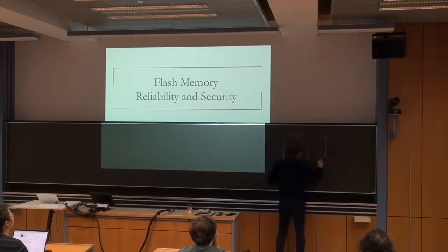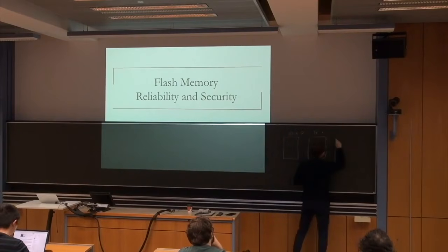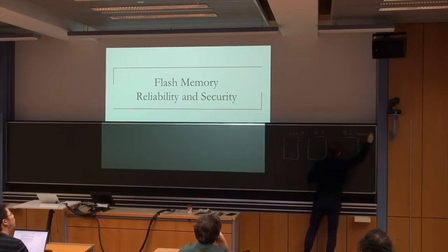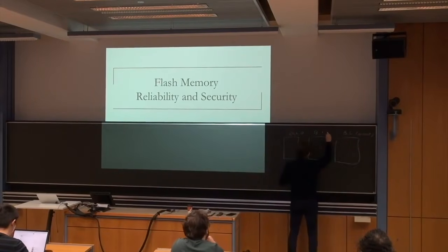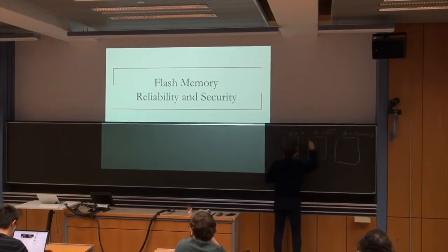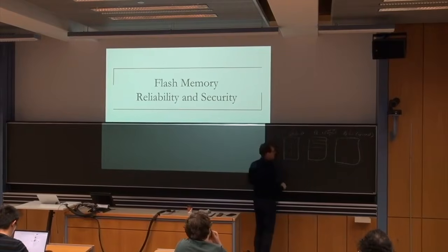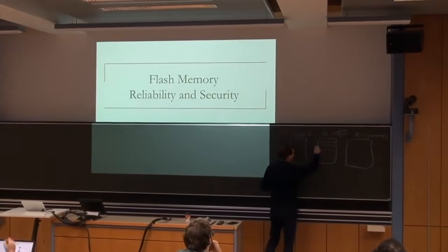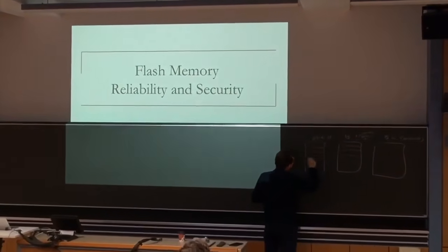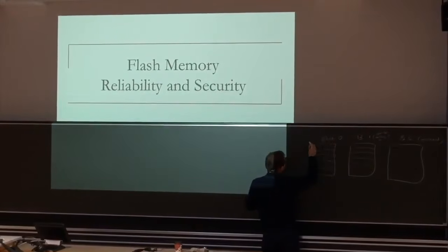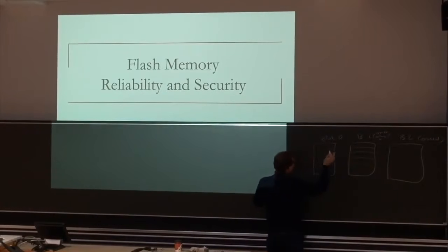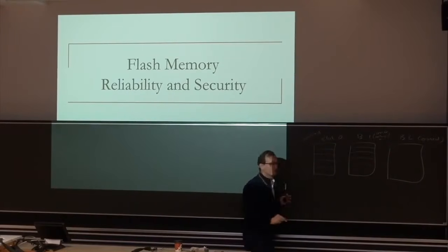We have block 0, let's say block 1, block 2. Let's say this is completely erased somehow. And this is the block that you're writing to. So open for writing, I'll call it. Meaning some of them are erased and some of them are being written to, because you've just erased it and you're directing your writes over here. And this is a block that is basically, let's assume that it's not erased, it's not open for writing, it's populated. So these are 3 different types of blocks.